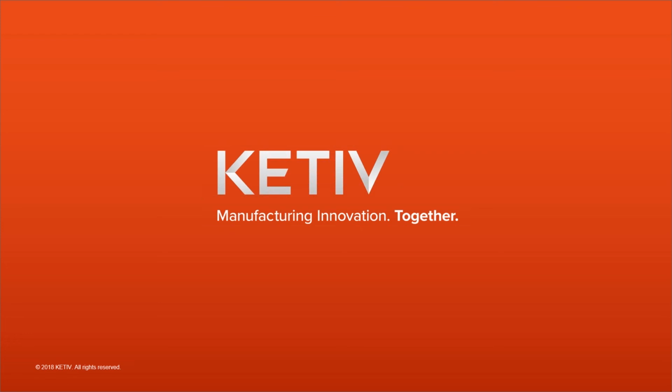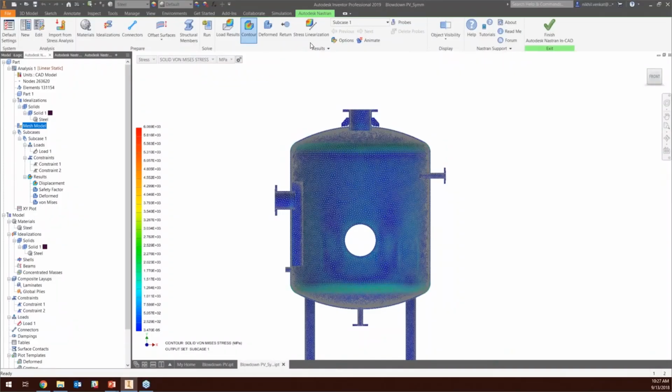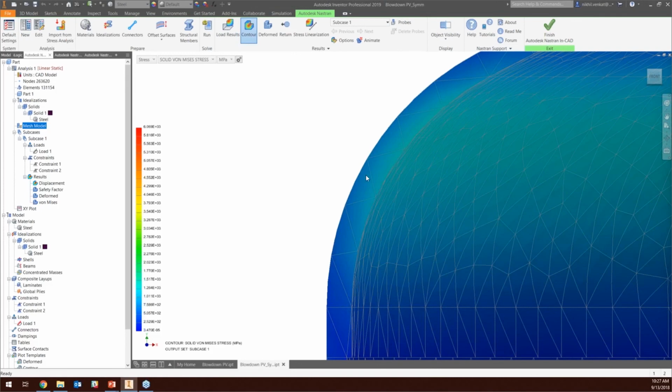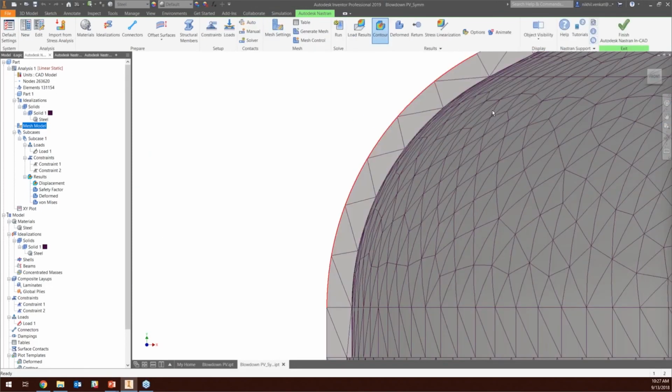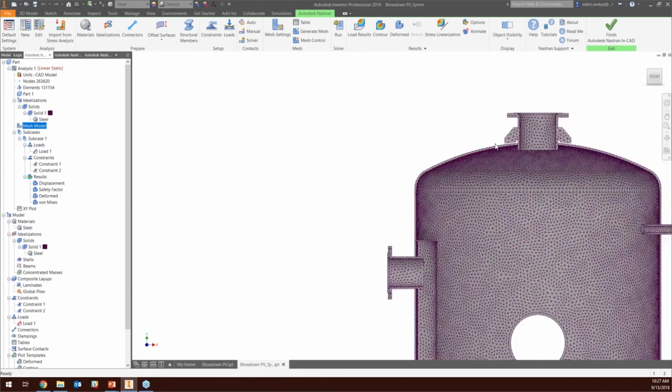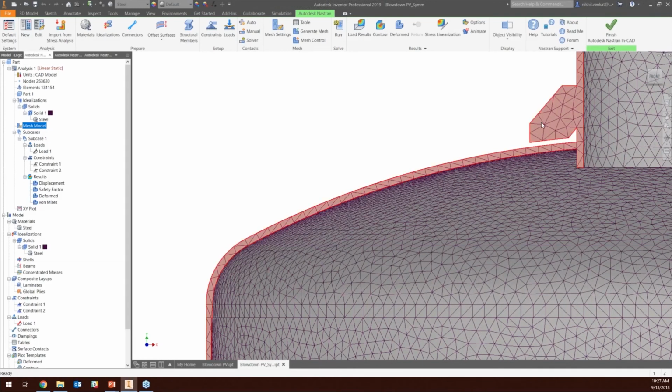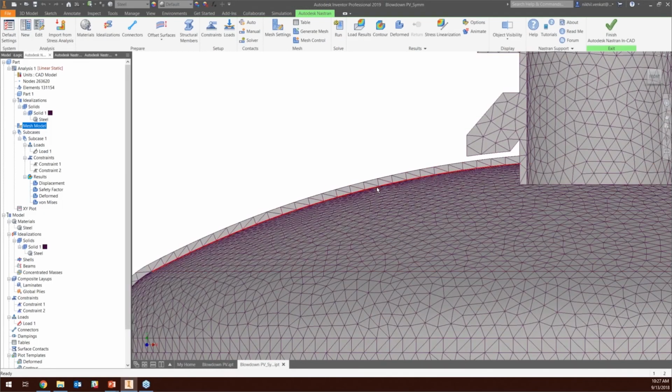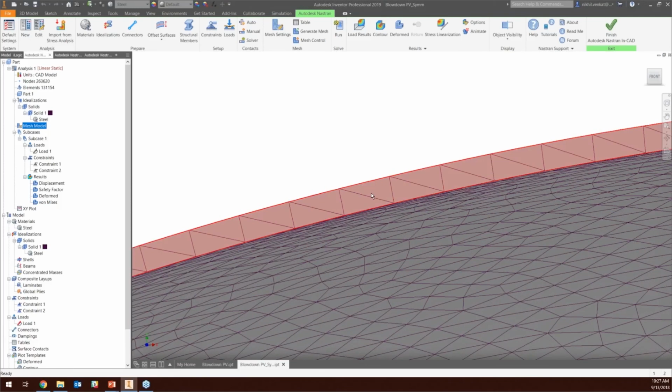First off, is there a particular recommendation for number of elements, specifically solid elements, in a through thickness direction? I'm assuming it's through the thickness here. Yeah. You want at least one element. I think most of the time the meshing engine forces you to have at least one element in there. It fails otherwise. So you would want at least one element, but again, it depends on what you're expecting to happen through this thickness, right?